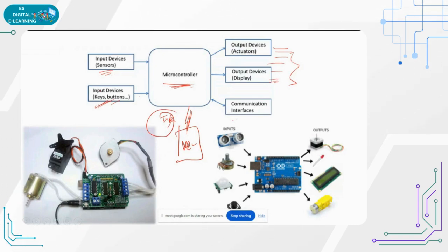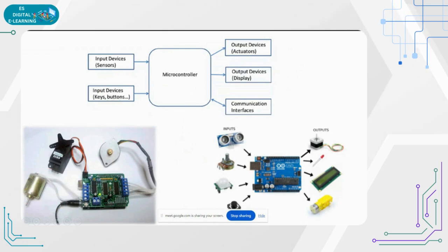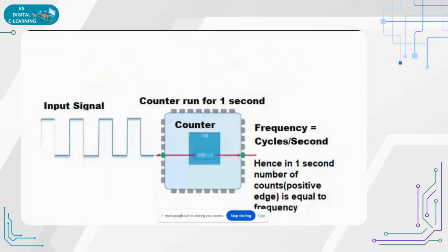So in the diagram, we were able to see there is the controller. Here we have the motor. The additional motor is a different motor, and we are configuring it here. And additionally, there are some other devices, the sensors we are connecting to it. Okay, and additionally the fan. So we are just doing the connectivity of the devices to the controller, and whatever the analog input or digital input, that we are giving.